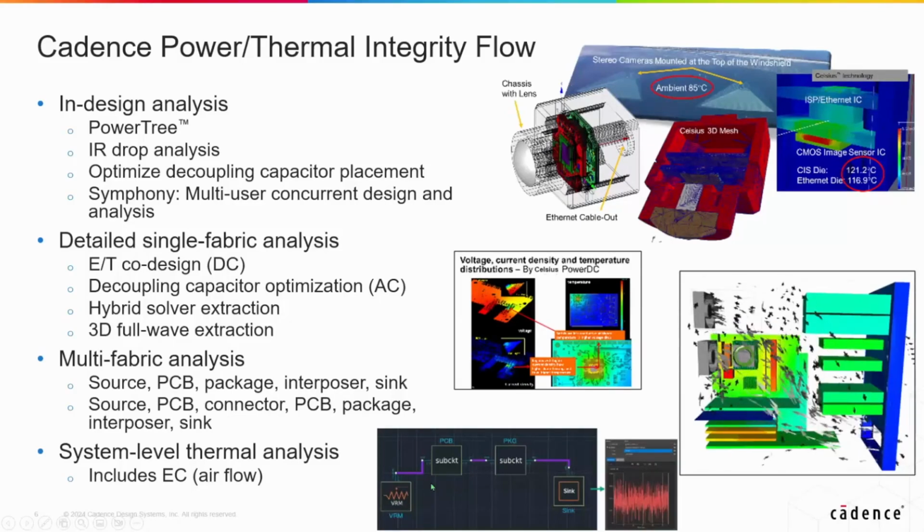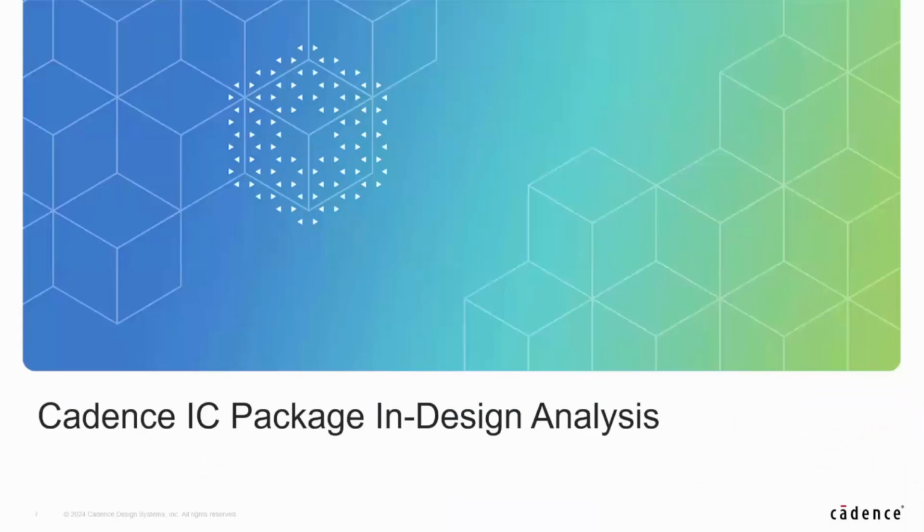We can look at both the IR drop, the AC analysis, making sure that we're meeting our target impedances, and we can look at voltage ripple as well. And ultimately, we like to encourage our customers to put this into a full 3D environment where you see the board, the packages, any fans can be considered as well. We're looking at the electronics cooling and making sure that the system is going to work from a thermal perspective.